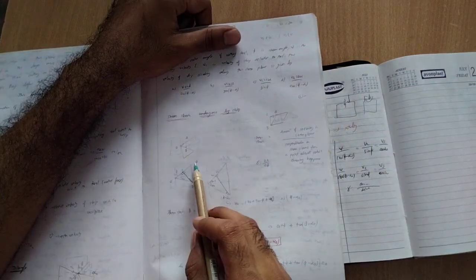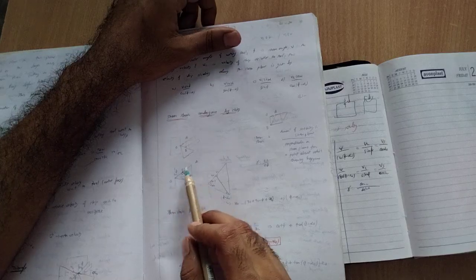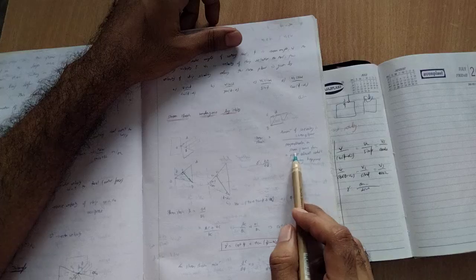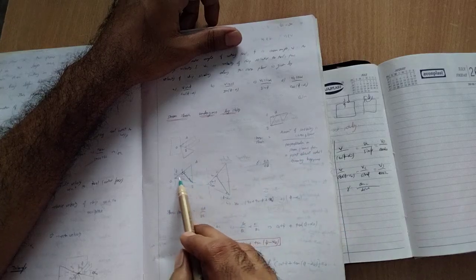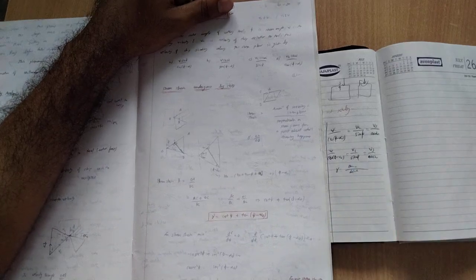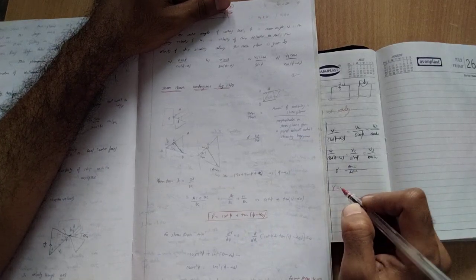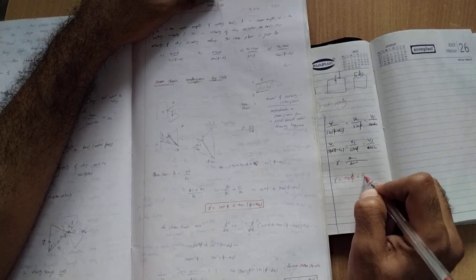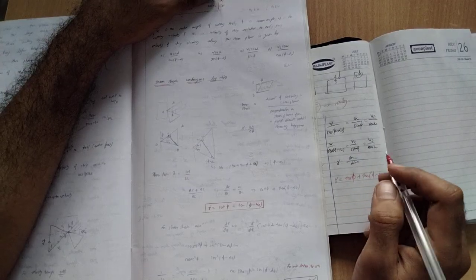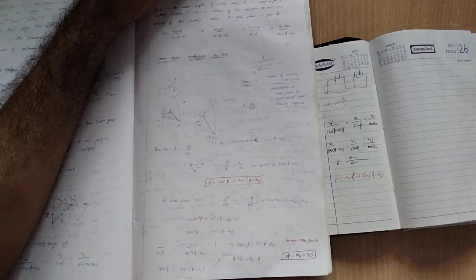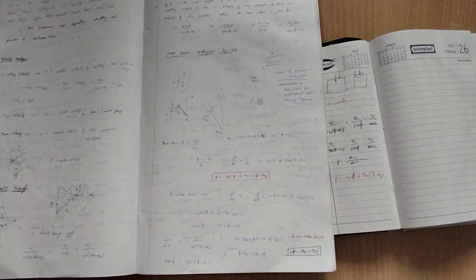OA is the amount of shearing, the entire shear. Next, OB is the perpendicular distance to the shear plane at the point where the shearing occurs. So just remember the formula: shear strain equals cot of shear angle plus tan of (shear angle minus orthogonal rake angle). For the minimum, we need to differentiate this expression.